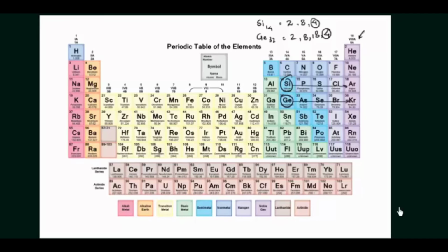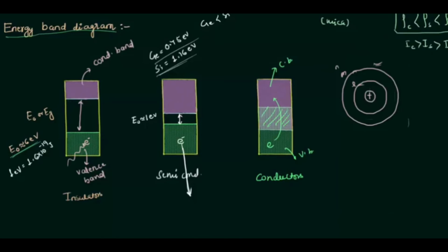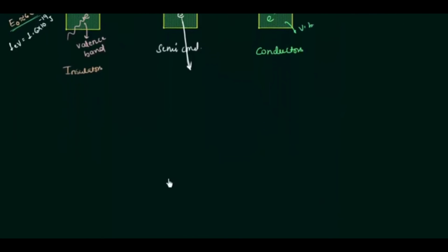The unique qualities of germanium and silicon are due to their atomic structure. The atoms of germanium and silicon form a definite pattern that continuously repeats itself. One complete pattern is called a crystal, and the periodic arrangement is called the lattice. In this presentation, when I make the atomic structure for silicon, I will explain what this pattern is and how we can have this pattern by the covalent bond. Okay, I will make the atomic structure for silicon quickly.